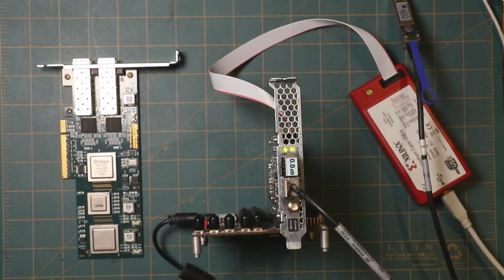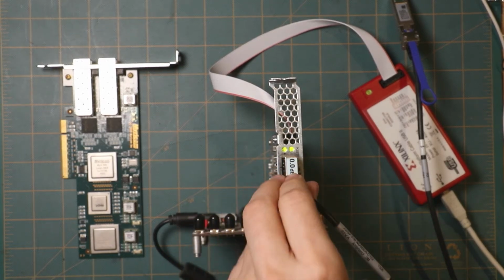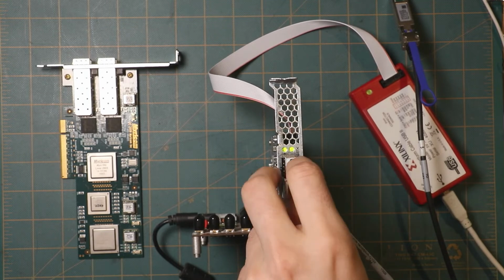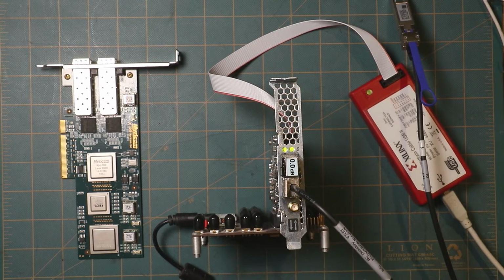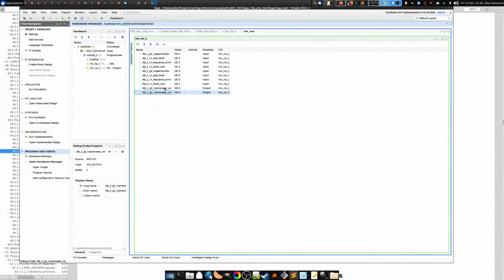I think I need to do some work on the reset side in order to make this work, because it looks like this is not going to cooperate today. Well, yeah. Let's see here. So block lock is high, sequence error is high, bad block is high. So presumably that would have triggered the reset. Well, let me put it to you this way. It seems to be resetting the transceiver, so that's a start. But obviously there's a few things that need to be sorted out.